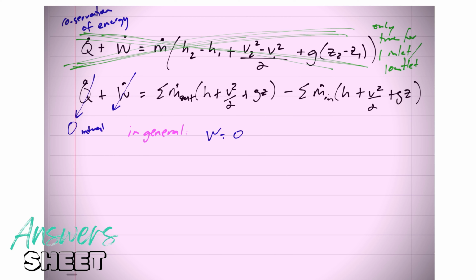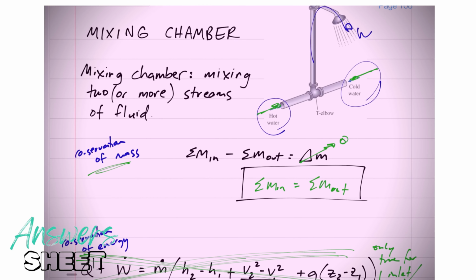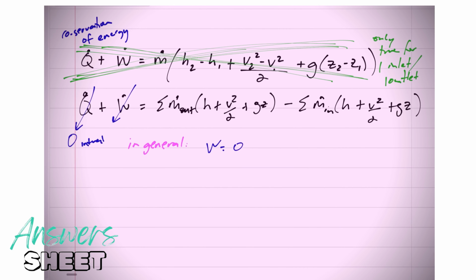When we're looking at the whole conservation of energy of the whole system, yes, there's heat transfer back and forth between hot and cold, but if the hot and cold are both part of our system, then there's no Q. In general, there's no Q. It is internal. Unless it tells us there's some Q going out, but in general, the Q is 0.